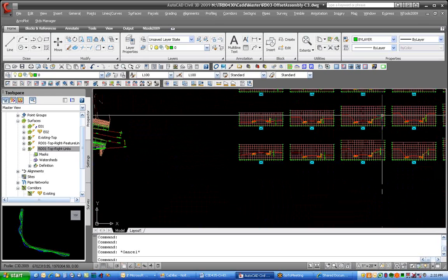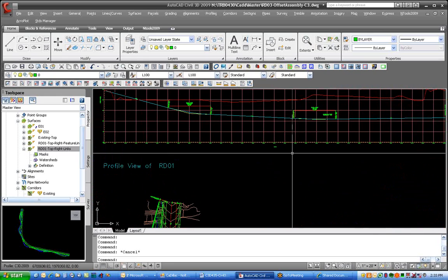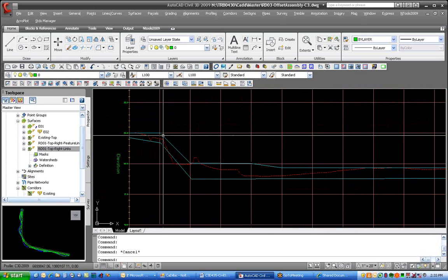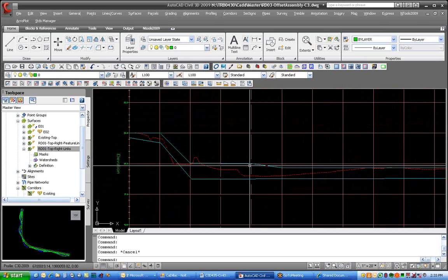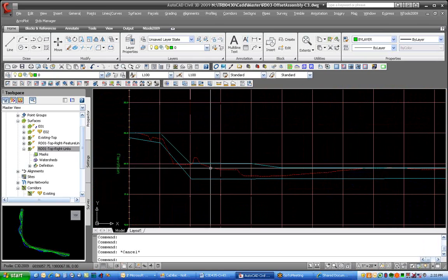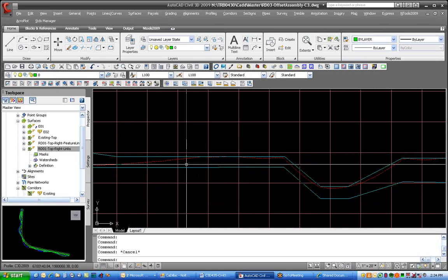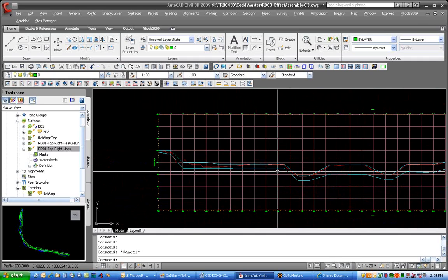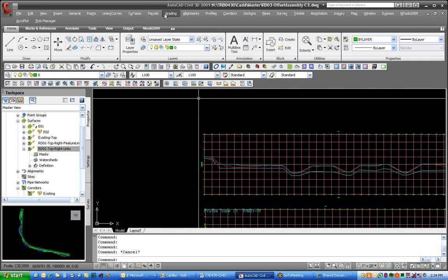and it's not quite, bear with me as I go over here. I'm using these two profiles here, so you can see I'm making my wall higher than existing, but they build the walls that way anyways. You don't want your wall following that, and I've tried to put in flat tie-ins where I can. We can also do profiles for the top of wall, and we'll show you those sub-assemblies I made,